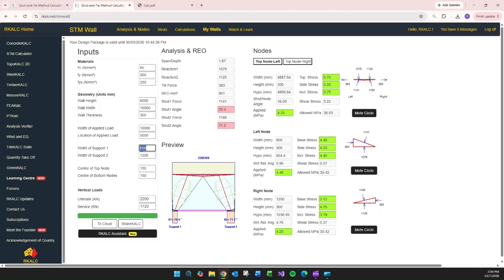But here, the whole wall is being loaded uniformly. Now we look at the width of the support, 1200, these two columns down there, and then we put the loading, which is 25,000, and the service load becomes 25,000 roughly. To convert it to SLS, you just divide by 1.3 roughly from experience. So that is what you see here.